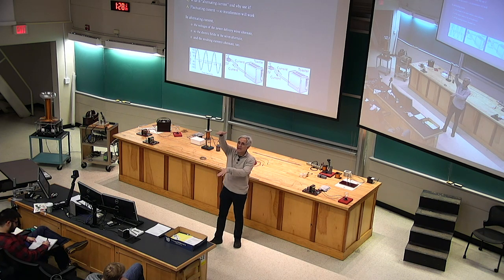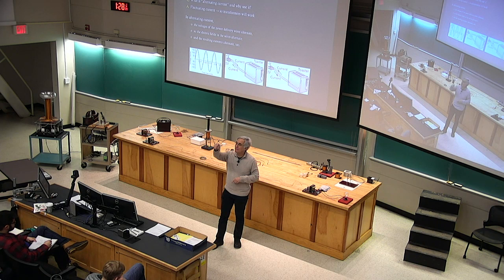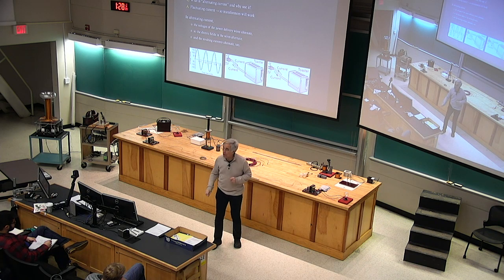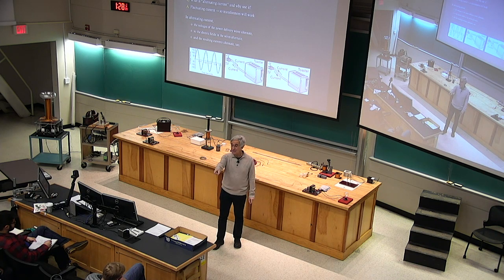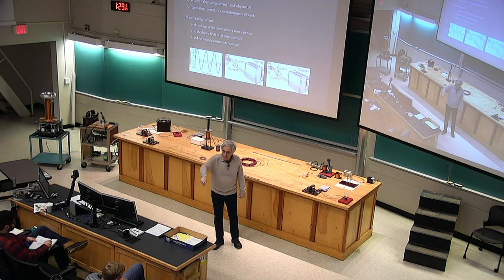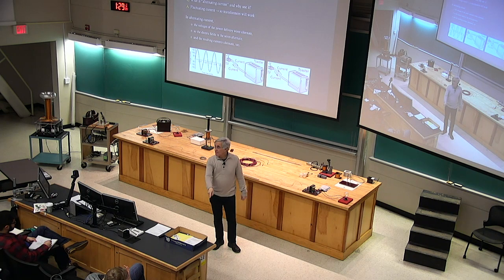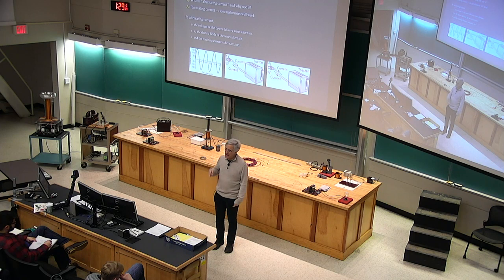So when power is in the positive voltage range, current flows out of the power slot in the outlet through the wires into the toaster, through the toaster filament, and then back out neutral. When the voltage of power is below 0, current goes the other way. Current originates in neutral, flows through the toaster's filament, and departs by way of the power wire, because it's the lower voltage at present. So current's going back and forth.